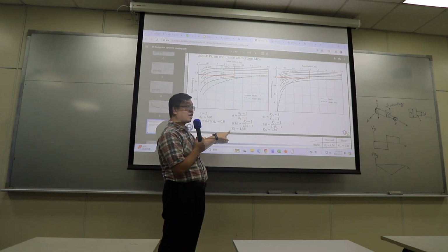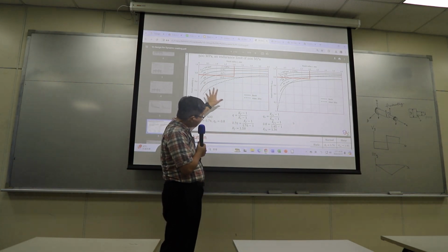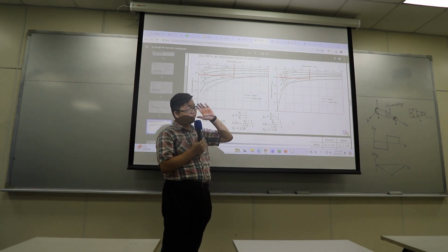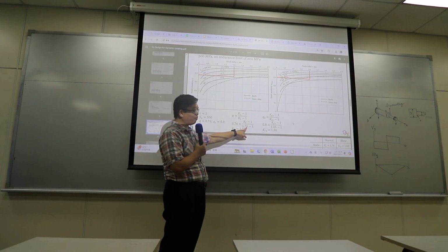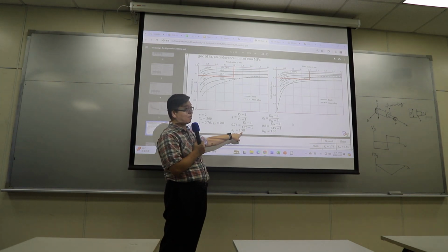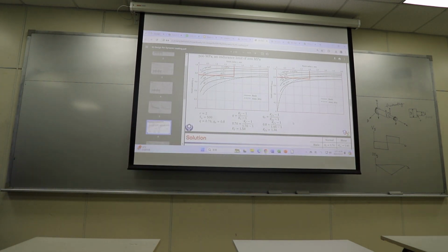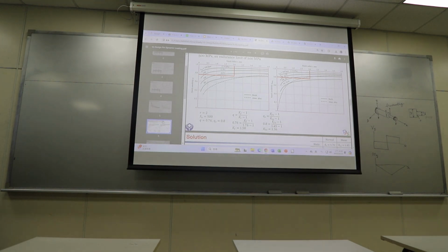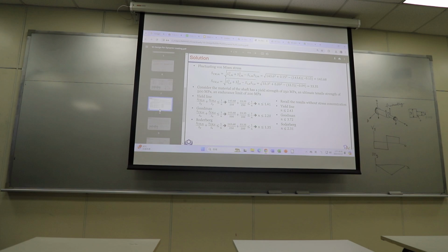By calculation, KF becomes 1.58. So you can see for this loading condition, for this geometry, the stress concentration for static is 1.76, for dynamic is 1.58. So once you have those, you will apply specific fatigue model right here, okay?